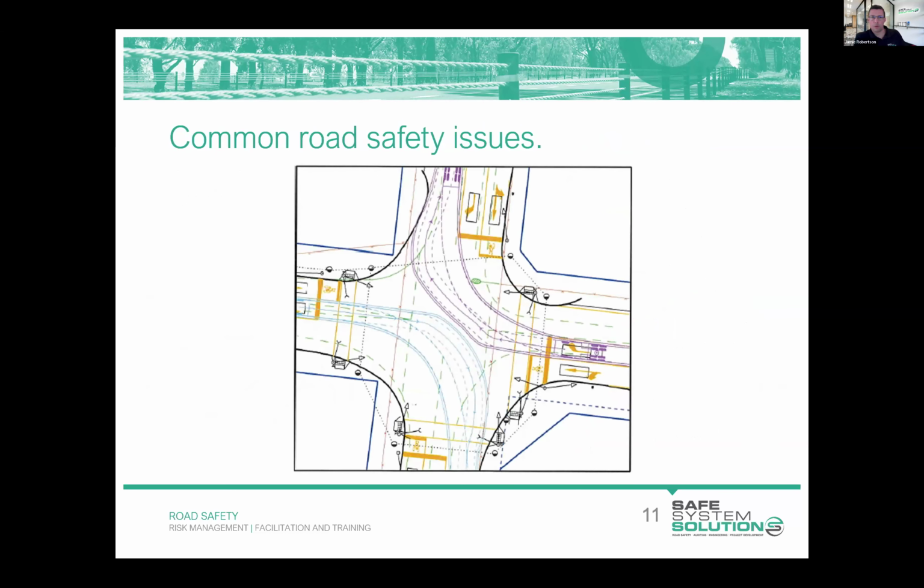There's an example of a swept path diagram, and there are lots of lines going on there, and it is important to understand what those different lines represent. I hope you can see my cursor there, but if we consider the purple vehicle, you can see parallel lines on either side. The outermost line is an offset line, and Austroads talks about a 0.5 metre clearance from the vehicle body, that we should provide that 0.5 metre clearance to roadside objects, including curbs. So it's common to show that sort of offset line.